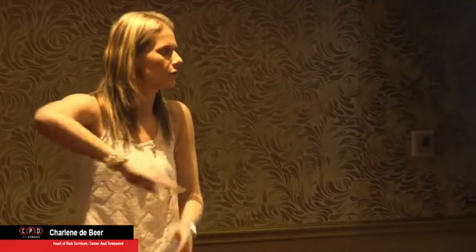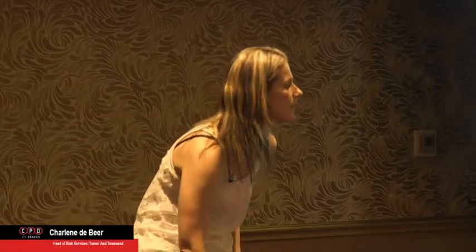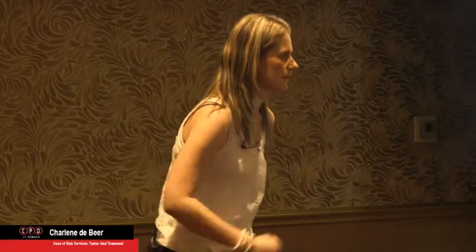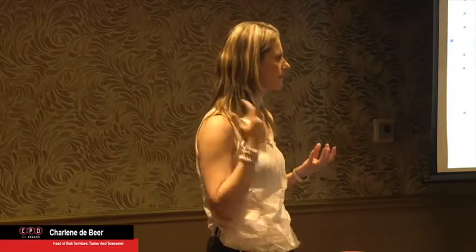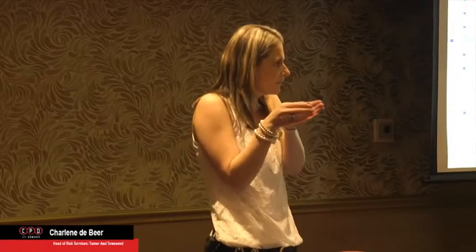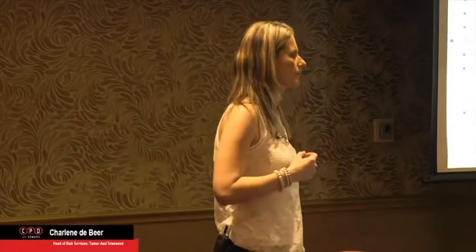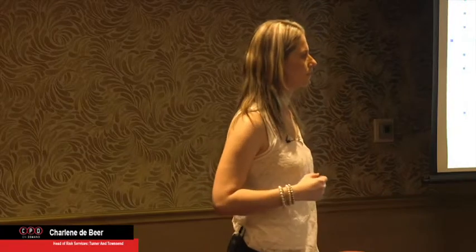It doesn't know where it has to finish, so it will just run into eternity. As well, with a risk loaded on the schedule, I'll pick up how much float there is. So if I say it's a 10-day delay and there's 5 days of float, it will just push out that activity by 5 days. It won't keep the 5 days float and then attach another 10 days. It's got a lot of logic around it: you're telling me it's 10 days, I've got 5 days of float, it's only going to impact 5 days. But if it's a parallel activity and it stops there, and it's not driving your longest or critical path, it also won't move your date. But if it is a driver, it will shoot out your date.